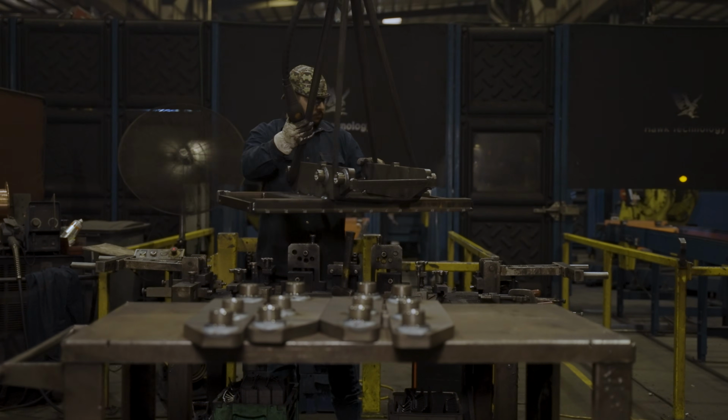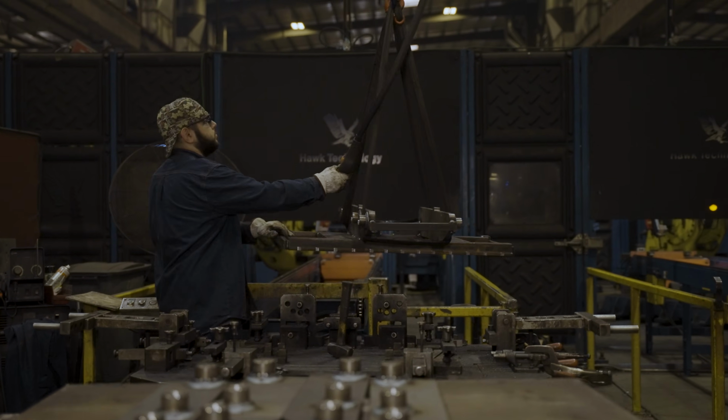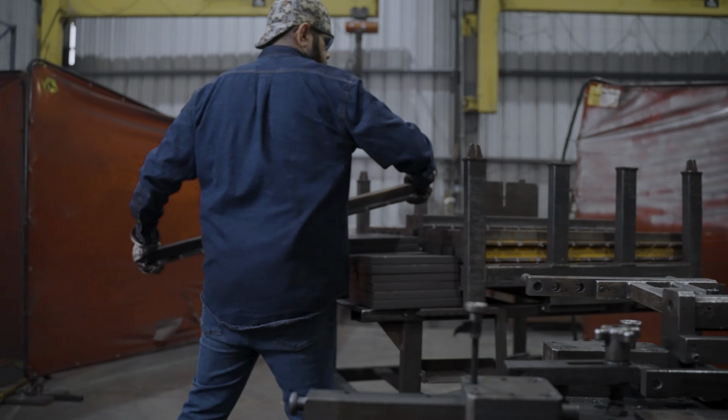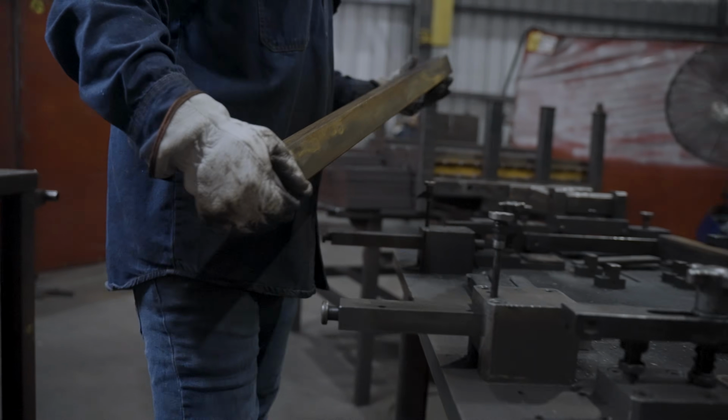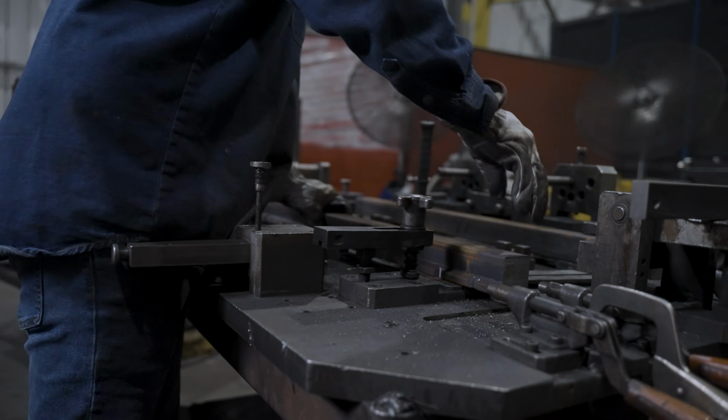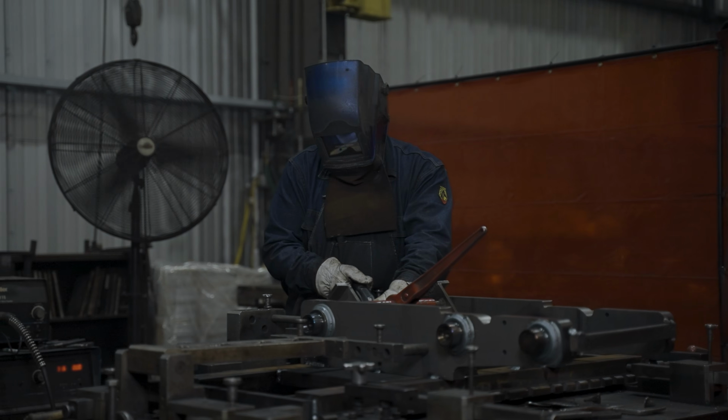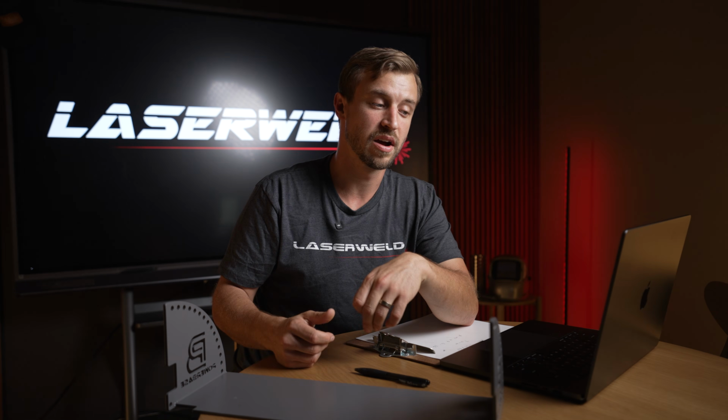If you're the welder, I would highly suggest you even mock it up. I have totally sat in my office and mocked up picking up the parts, setting them in place, getting the pliers, cleaning the gun, putting the hood down, running a bead, flipping it over, grinding it out. We've mocked all that up with a stopwatch, and we've come up with a time on exactly how long the part's going to take. And normally, we're pretty dead on.